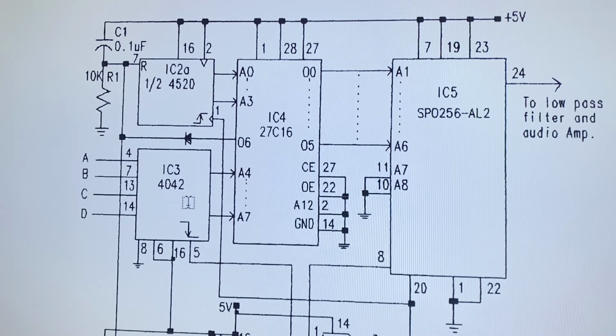Once the latch addresses one of those 16 different blocks of memory, the scanner will scan those bytes available. Sometimes, of course, you don't need the 16 bytes for every block of memory. So this is why you have the output 6, which will clear the counter, and once the counter is clear, it'll go back to the initial address where it is scanning.